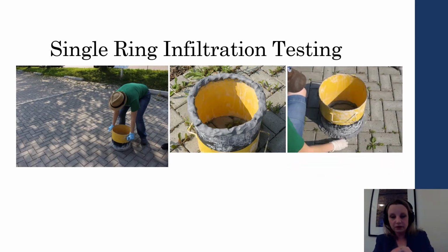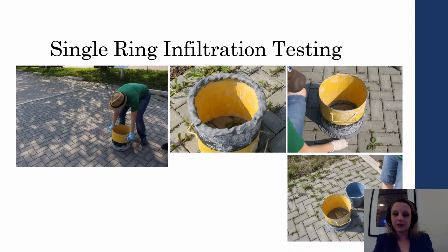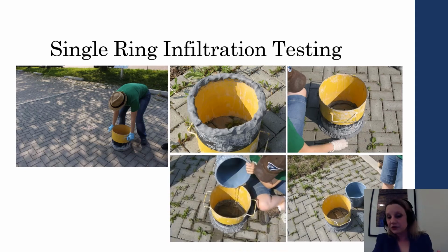Any sort of openings along the joints are sealed, and then we apply a known volume of water. Measuring the time it takes for this water to infiltrate is a data point that then we can repeat, once a year or once every 6 months. And this will let us see and then also anticipate when we are going to require maintenance for our pavement.